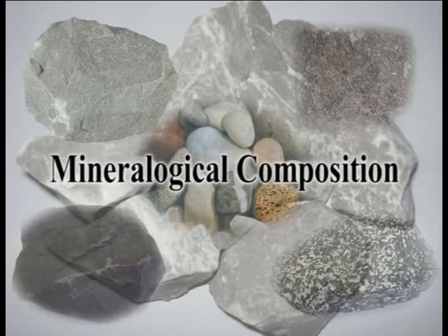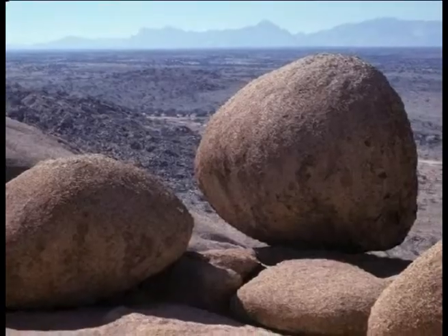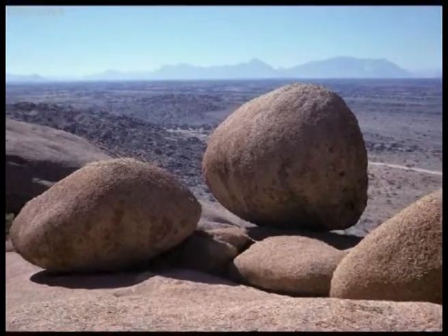Mineralogical compositions. As rocks are ultimately made up of smaller units of minerals, their properties depend upon the nature and composition of these minerals. It has been observed that rocks composed chiefly of silica, that is SiO2, especially in free form, are the strongest in all respects. Quartzites, sandstones and granites are some examples of this type of mineral composition.